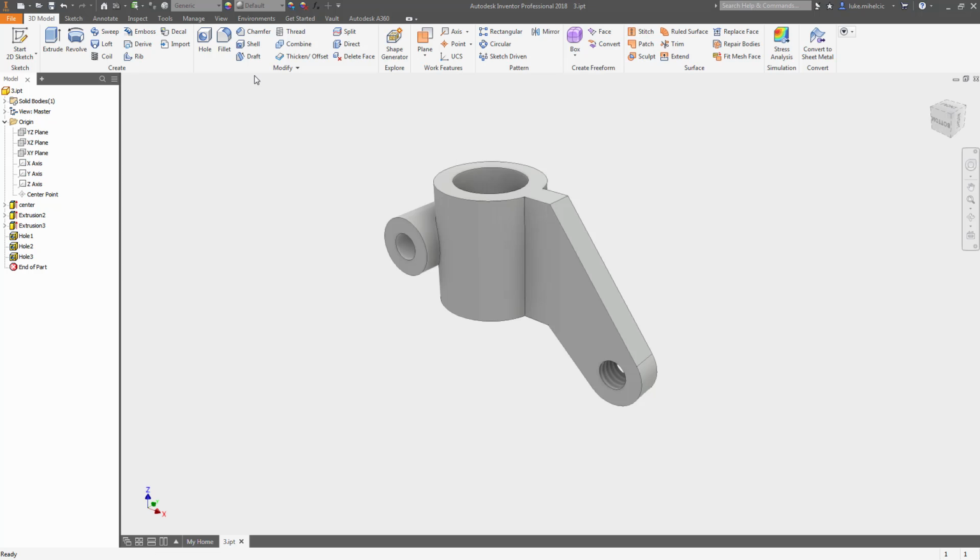And you go to add your last fillet and it won't take. And then you undo the previous fillet and try it. It doesn't work. And you undo your previous fillet and you try it. Again, this is something that has served me for years and years and years running Inventor. If you do them from smallest to largest, you tend to have better success of getting all of those fillets applied. Sometimes you can't help it and you have to do it in a different order, but just keep that in mind. Do your fillets last and do them in order from smallest to largest if possible.